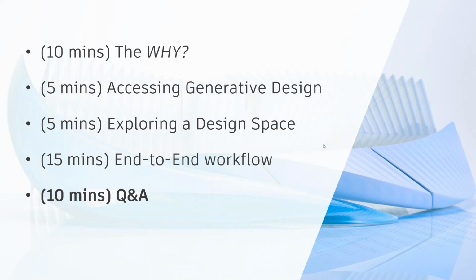With the workflow that Ali showed, where you're leveraging that Inventor part in Fusion, all the preserve and obstacle regions will be updated, but the outcomes are a snapshot of when you submitted that simulation. So all the outcomes would be based off of where they were when you submitted to get those generated.